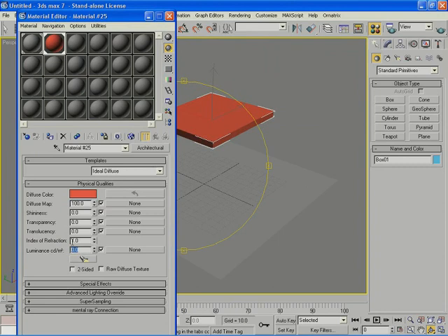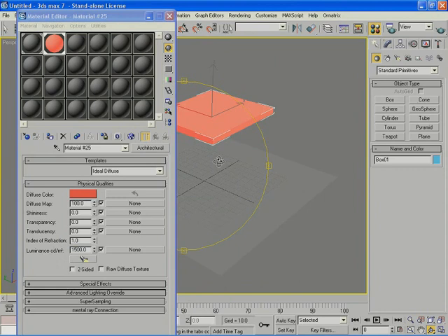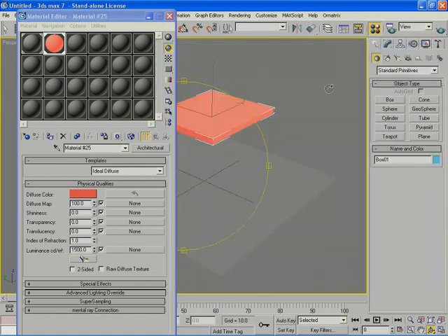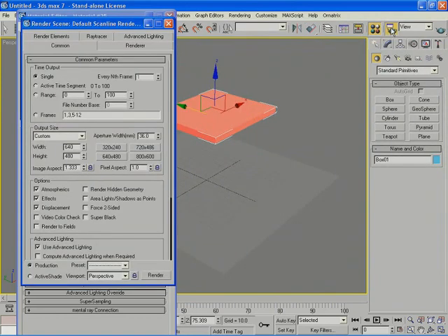So this looks like a self-illuminated surface, and it has nothing to do in terms of lighting with respect to any other surface. I'm going to activate mental ray by going to the render scene dialog, and from here I'm going to choose under presets mental ray, no global illumination high. This means that there won't be any global illumination in this setup. Of course, I can change that.